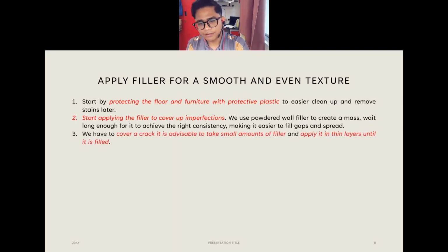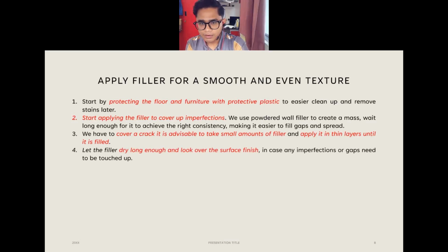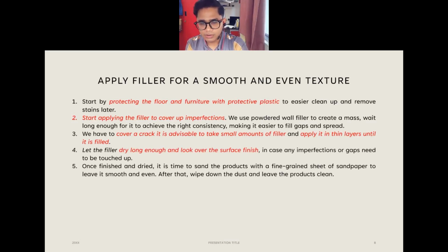To cover a crack, it is advisable to take a small amount of filler and apply it in thin layers until it is filled. Let the filler dry long enough and look over the surface in case any imperfections or gaps need to be touched up. Lastly, once finished and dry, it's time to sand the product with a fine-grained sheet of sandpaper to leave it smooth and even. After that, wipe down the dust and leave the product clean. So that's all from me.